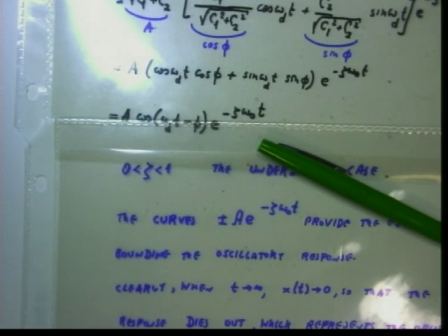This we knew from free undamped vibrations. Please write it down. Again, when zeta equals 0, e in power minus zeta omega sub 0 t equals 1, and we have harmonic variation. Now, this harmonic variation we had when we had undamped vibrations. So everything makes sense. When zeta goes to 0, we are coming back to our old friend, that is undamped vibration.